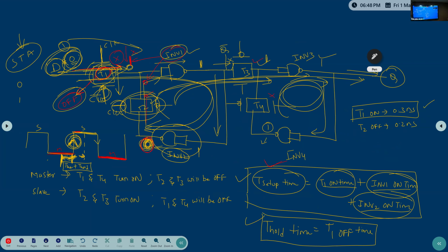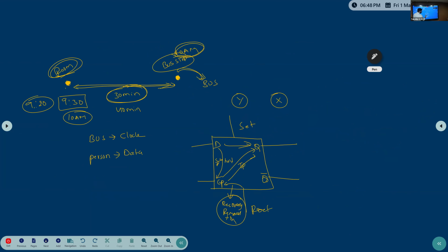So the timing arcs, when you observe: D to CP pin will have a setup timing arc and a hold timing arc. From the CP pin to Q pin, propagation delay will be there. Clear? These timing arcs are very, very important. You will observe these timing arcs in the .lib file, which is one of the input files for PNR, placement and routing.